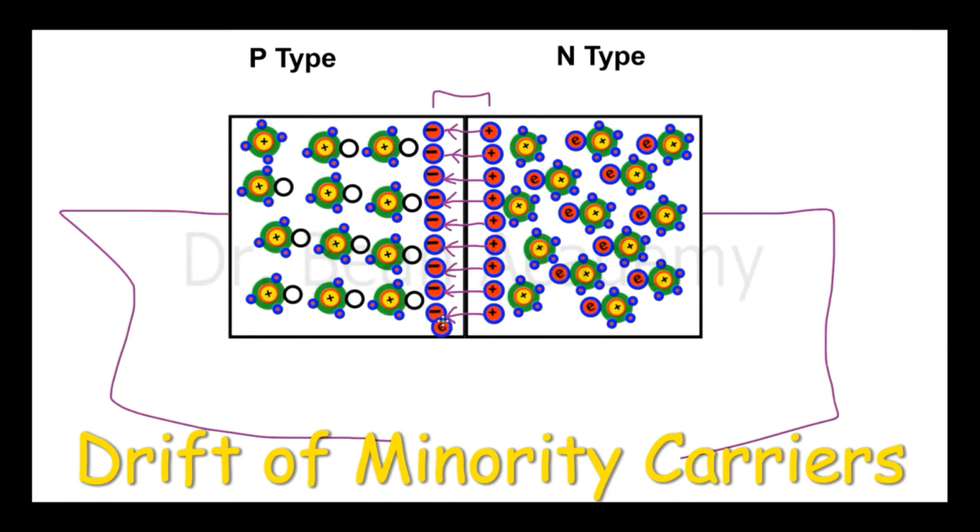And if somehow it crosses the series of these negative charges, it can sneak through and go to the middle of this potential barrier. Now it's easy. It will get a repulsion as long as it is on the left side of this vertical series of the negative charges. But if somehow it crosses this barrier and reaches the middle, it will get a push from the negative charges towards the n-type.